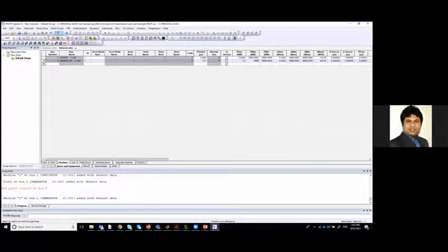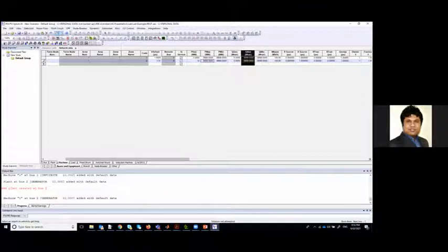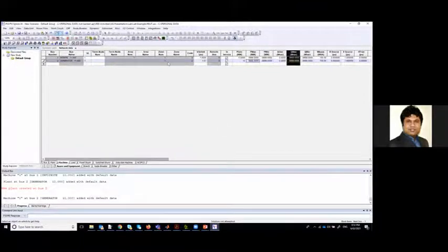I want to bring some attention to the fact that most generators in real time have minimum and maximum generation capacity. What is the minimum for the operating condition, what is the maximum; you can put that limit, especially for activity 1, which I asked you to practice yourself. For the generator, P limit and Q limit are given. If you have a source impedance, you can put it. If it is coupled with a transformer, you can put the transformer resistance and reactance here. But I tried to keep it simple here.